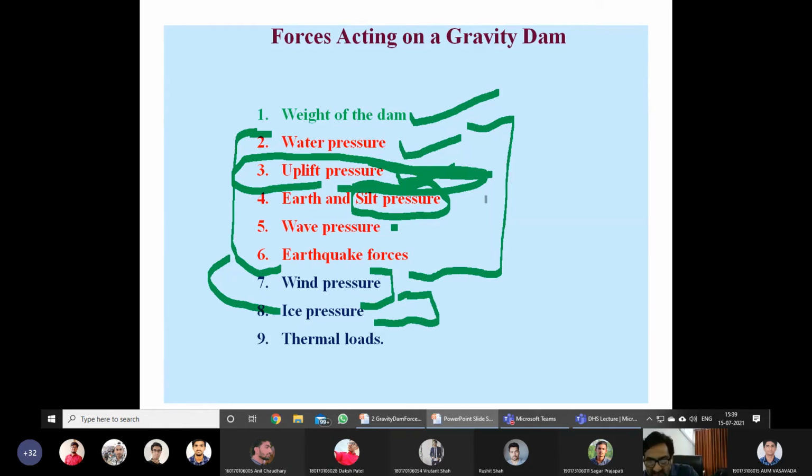See, the reservoir water which is there, the top layer gets frozen, and the formation of ice means volume expansion, and that expansion of volume on the surface of the reservoir exerts some pressure on the wall, and that too on the top of the wall. So that is something horrible in case of ice pressure and the problems of ice formation in colder regions or cold countries.